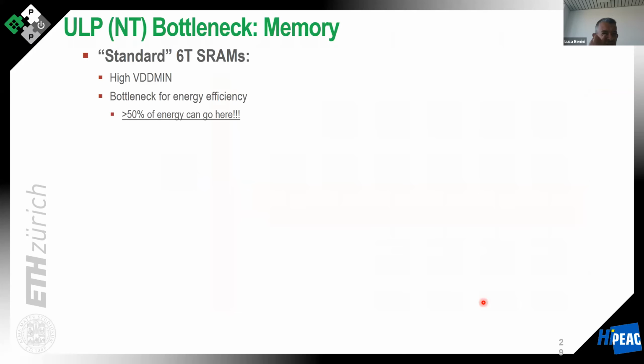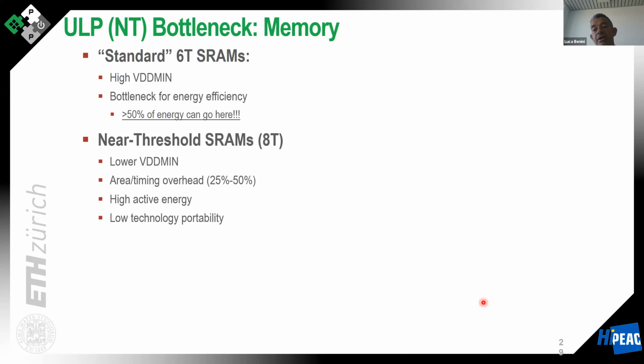First of all, we need to really decrease the cost of accessing this memory, because this is the most dangerous memory to have a high cost on. Why? Because this memory is accessed every cycle. You need an instruction every cycle. And also, memories don't scale down very well with voltage. So in the instruction memories, you will need efficient memories that have a very low energy cost and scale down in voltage very well.